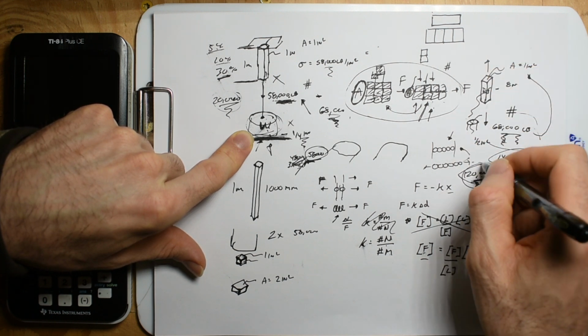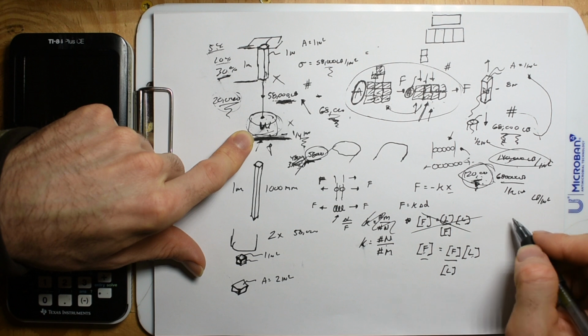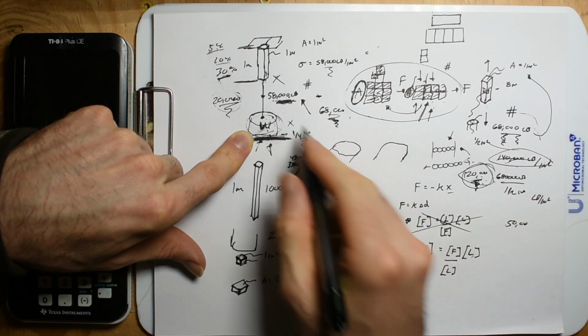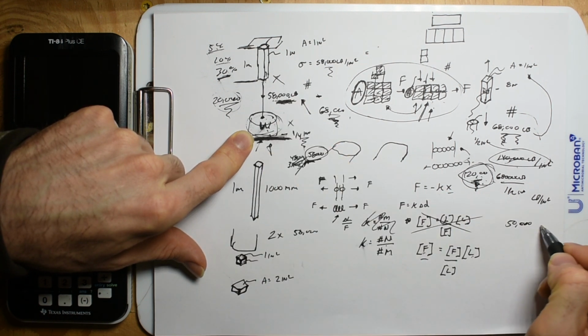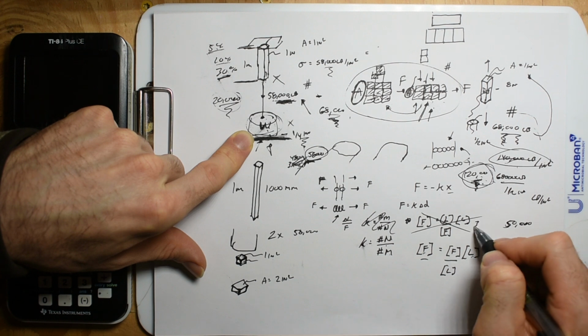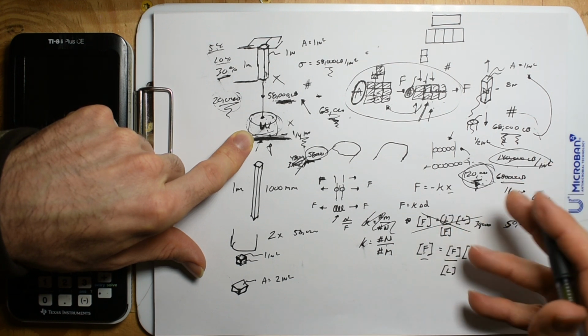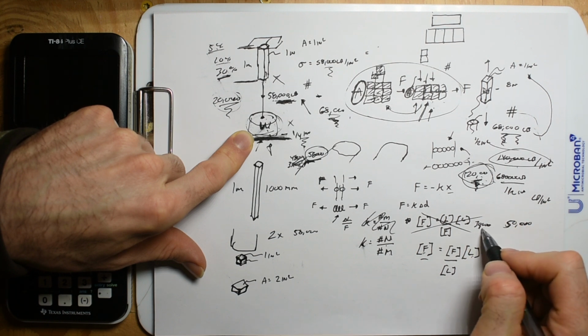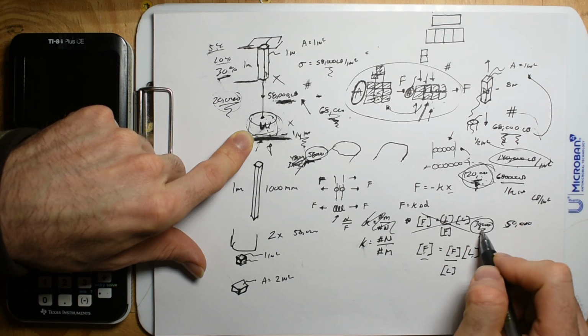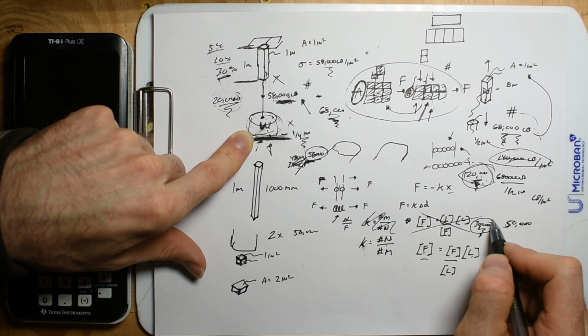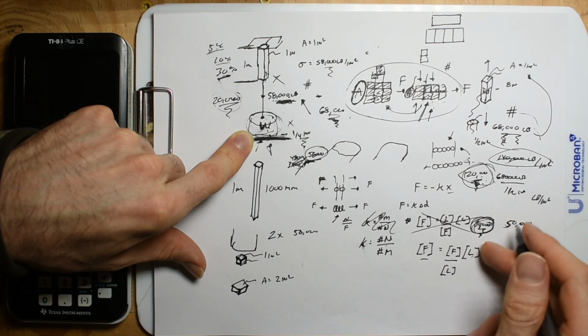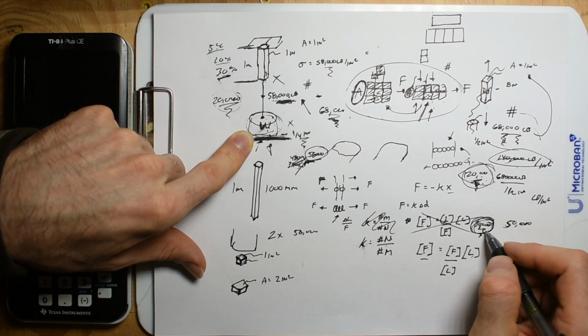This actually is tripping me out, because for steel it's 50,000. I use 58s because it's in books. But 50,000 for steel, it can be as low as 30,000, like just bolts at your hardware store, the low end. Low-end mild steel can be as weak as 30,000, and sometimes you actually use that number in some of the specific problems in the book.